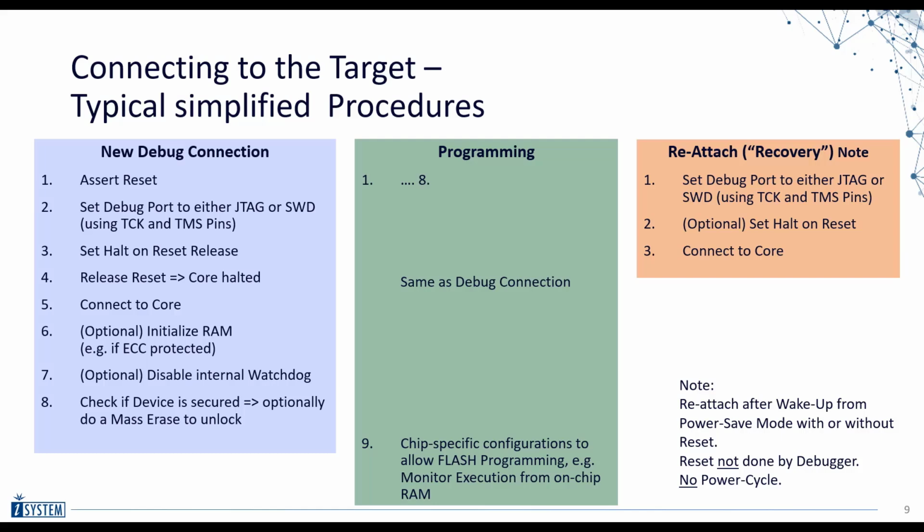Now discussing secured devices. At specific points within this sequence, the debugger may also check if the device is currently secured, for example, a flash protection is active. The user may then optionally disable such protections, for example, by performing the flash mass erase.